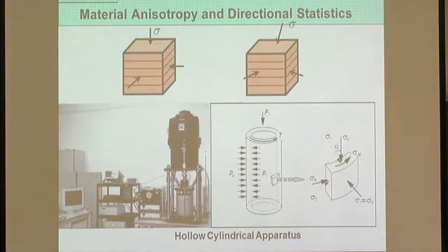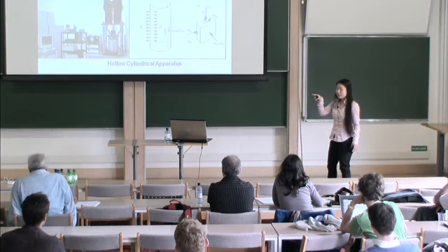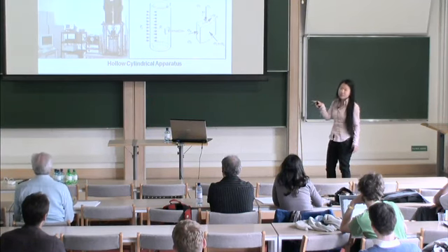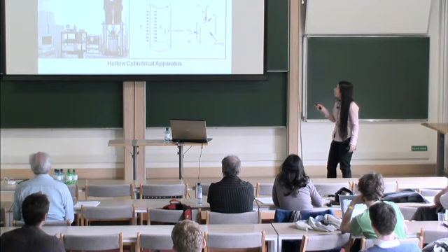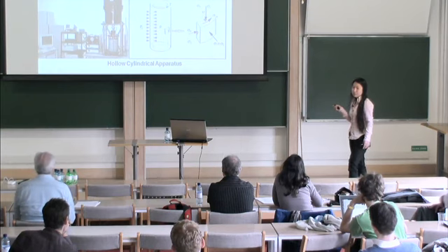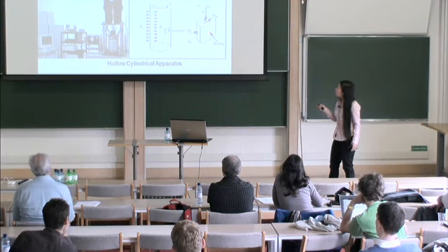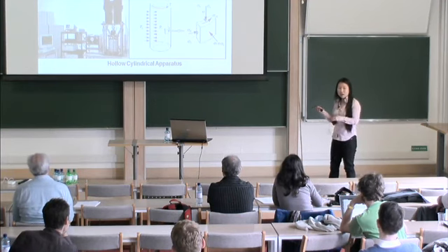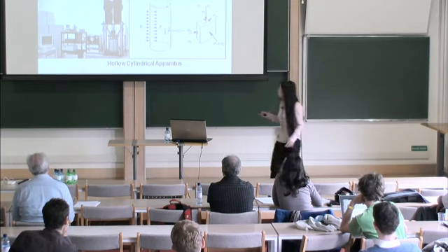The idea is we can rotate one plate on top, that gives a shear, and we can control the inner pressure and outer pressure. That gives us additional freedom to control the principal stress direction. If you think about a block on a table, the direction you apply force should be the direction the block slides. But unfortunately for soil, even if we apply loading in this direction, the deformation may not be in that direction. This is a big problem for classical plasticity theory, because if we don't know the stress direction, we don't know the strain direction, and we don't know how to handle boundary condition problems.